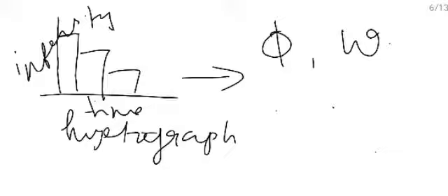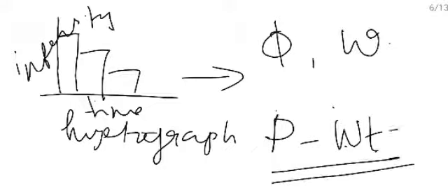So what we can do, if we have some depth of precipitation measured by the meteorological department, minus this W index times whatever time they have measured this much depth, will give you the total runoff. That is, if you have the depth of rain occurred as P, then P minus W into T will give you the runoff.